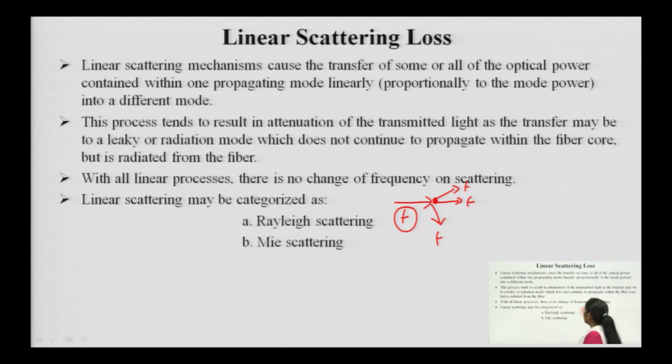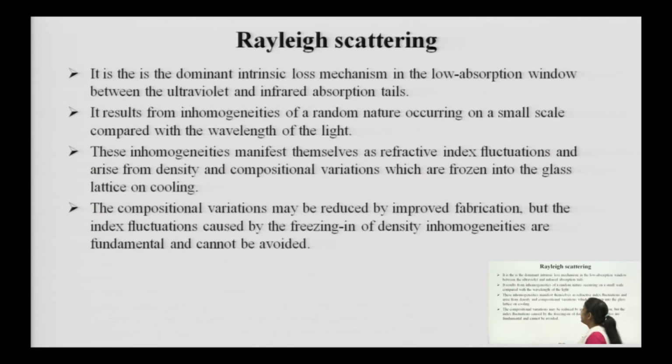Linear scattering, which may also be in the backward direction, may be categorized as Rayleigh scattering and Mie scattering. So we always keep in mind that there is no change of frequency and that linearity will also exist here. The basic principle which is applicable to linear scattering loss is also applicable to this one. Now, the Rayleigh scattering.